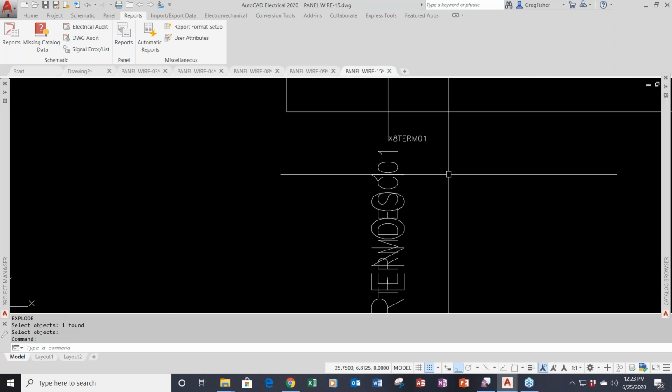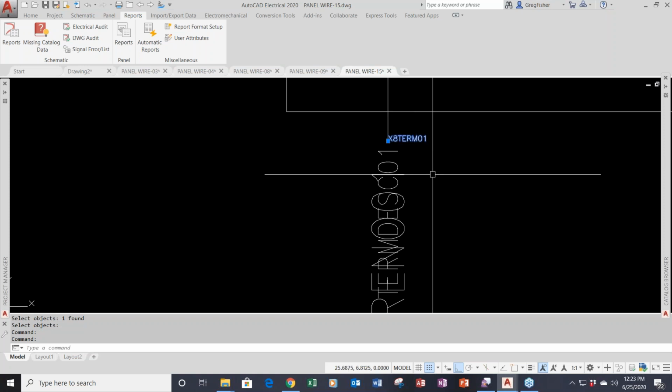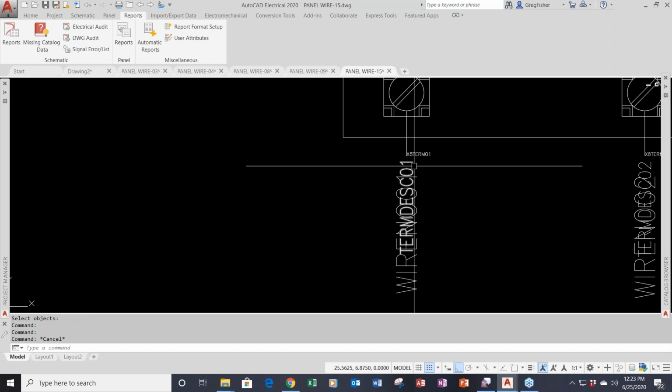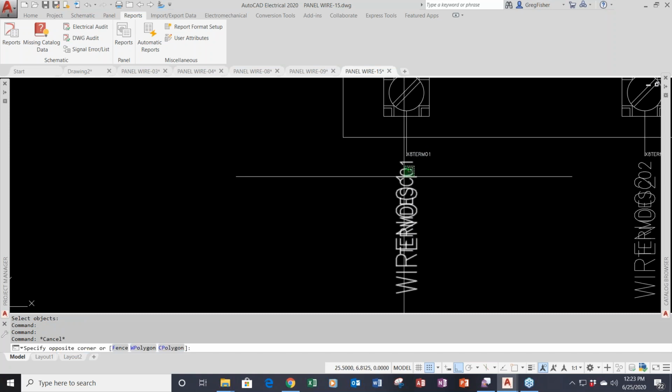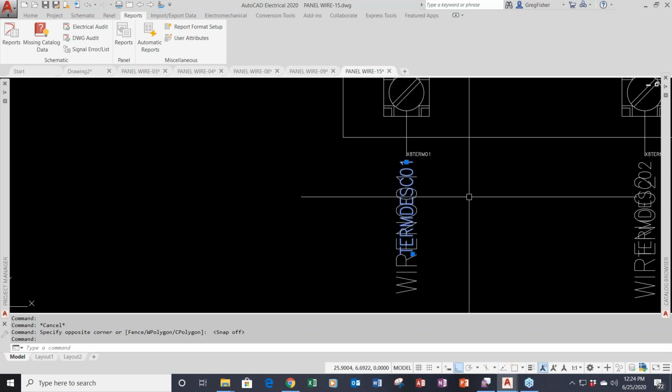Like I said, when you create a regular schematic symbol, you place connection point attributes down on a schematic symbol. You do the same thing with these footprint symbols. You actually put a connection point down there. I just happen to have mine right there. And then I've got the terminal description.